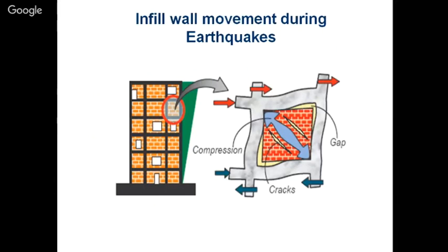That is definitely going to reduce the resistance level, and it is going to affect the global resistance of that particular building. So you are required to take the brick infill into consideration while you model the building in computer software. And when you include it, the forces coming into your columns are going to change accordingly, and the reinforcement and other things are going to change.